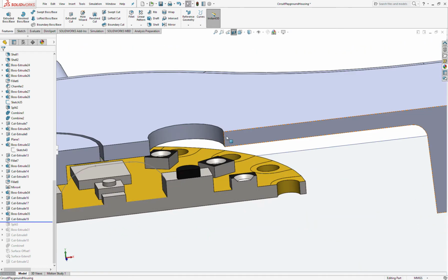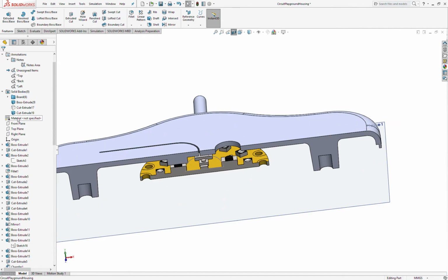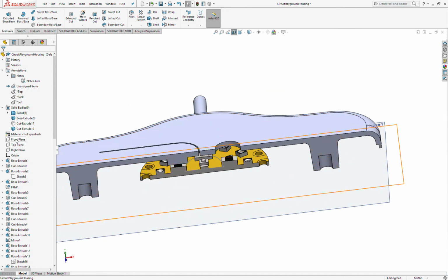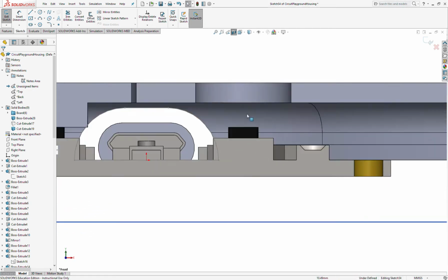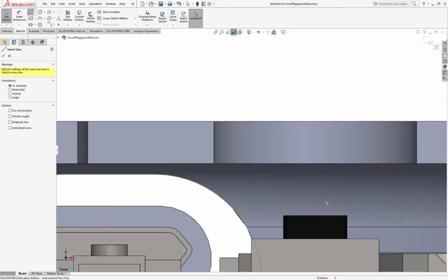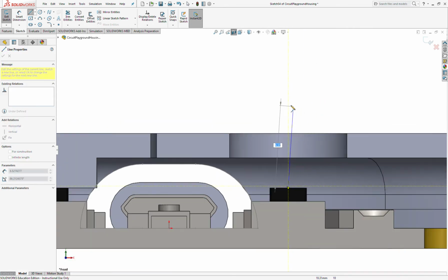Although I demonstrated in class with a series of extrusions, a slightly faster way, I guess, or just another way, right? to create sort of the button insert is with a revolve. So in this case, we're going to do a similar thing. Maybe we might leave a little bit of gap space so we don't have a false positive.